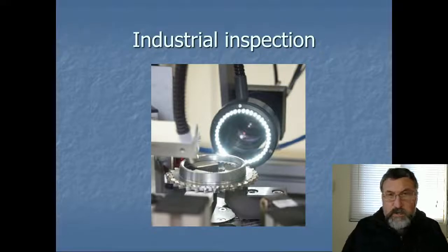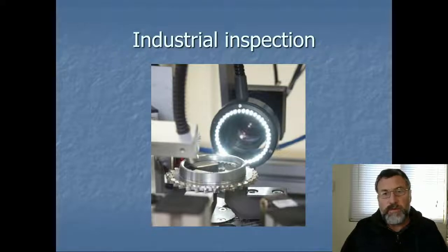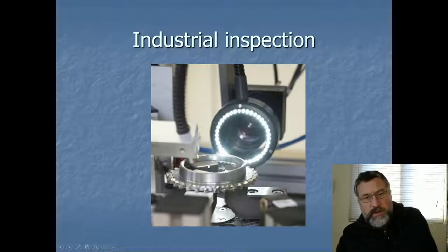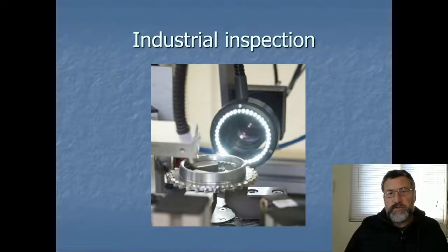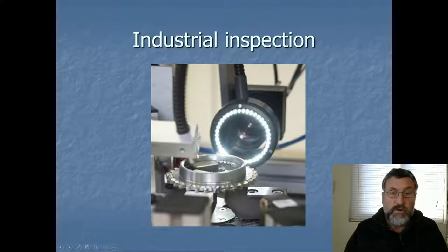Now, these were machined by means of dropping broaches, if anybody knows what that is, a type of tooling. You drop the broach through the middle of the hub and it carves sort of grooves in the hub according to what you want, according to what you're trying to manufacture. But if you didn't drop these broaches through in the right order, then you get the incorrect hub, which would look like a normal hub, but it wouldn't be quite right. And you put it into your truck, and then you find out there's a problem, and you've got $2,000 worth of work to replace a $2 part or something like that. So there's a big motivation. So we had a vision system where we were checking the grooves on the side of this synchronizer hub and checking they were as they should be to make sure the manufacturing had occurred according to plan.